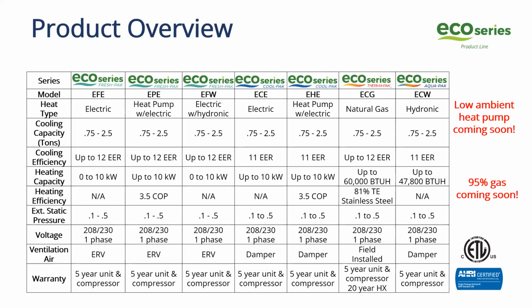So first it starts with the compressor only. Then if it can't keep up with the compressor, it'll kick in the electric heat and run the electric heat until it's satisfied, and then it'll back off the electric heat and continue to run on the heat pump compressor. So it will have a simultaneous operation, probably once you start getting below that 35 to 40 degree outdoor set point, but it's going to be based on the call from the thermostat and whether or not the unit can keep up with the compressor. It'll make the call whether to bring on that electric heat or not.